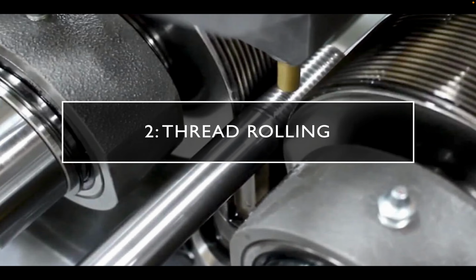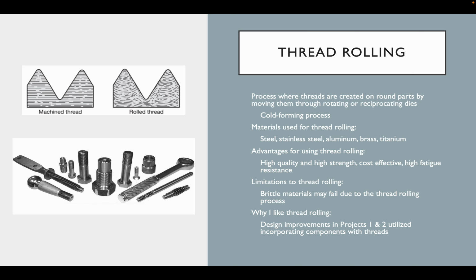The second topic I will be discussing is thread rolling. So thread rolling is a process where threads are created on round parts by moving them through rotating or reciprocating dies. So this is a cold forming process, which means that the round metallic piece isn't heated in any sort of way for these threads to be created. Some materials that are used for thread rolling include steel, stainless steel, aluminum, brass, and titanium.